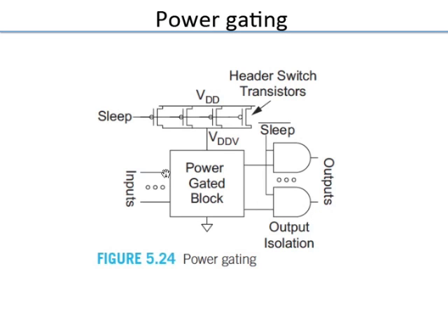So the question is, won't all the logic switch at the clock? But if you see, you can think of it as layers. As soon as the clock edge happens, the flops switch, then the first layer of gates take it, and so on. So you can think of it as a wave propagating down. The switching is like a wave which propagates down from the beginning flop to the capture flop.